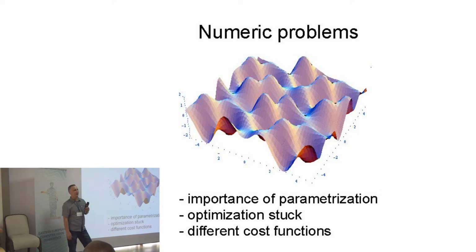Generally, we have no excellent ideal solution, but we can change parameterization of calibration parameters, of the camera extrinsics, of the point representation, and so on. We can use a different cost function, not only a projection cost function, but an angular cost function with not a Cartesian coordinate system, and so on. For example, when optimization is stuck, we can iteratively change the representation, parameterization, and cost functions to continue to minimize our error in different spaces.